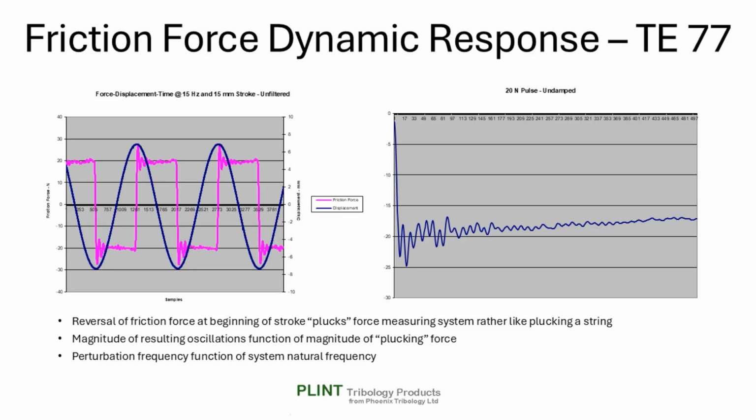and 15 mm stroke. The transition from static friction to dynamic friction at the beginning of each stroke and the resulting resonance is apparent in all unfiltered reciprocating tribometer friction force measurements, assuming that the measuring system has sufficient signal bandwidth. Whereas the initial peak signal at the start of the stroke may indicate the limiting static friction, the subsequent oscillating spikes are not friction effects.